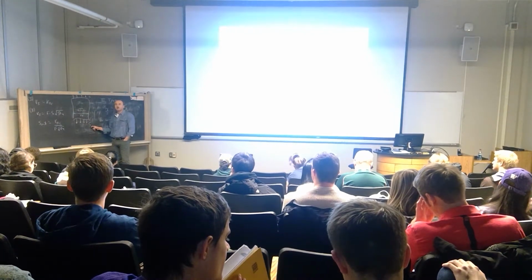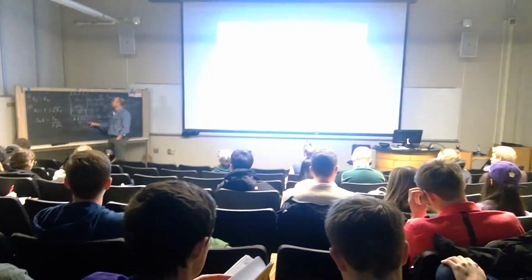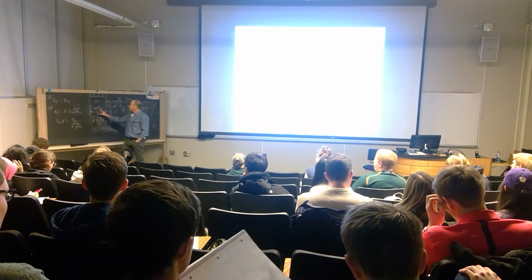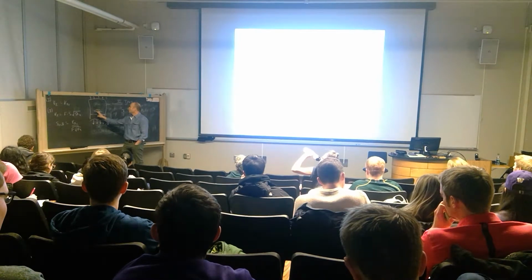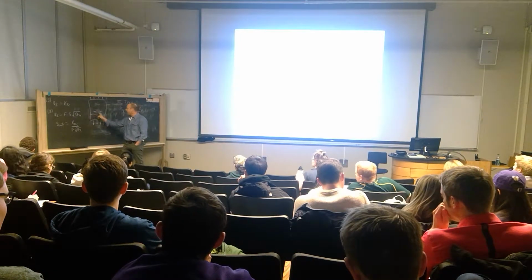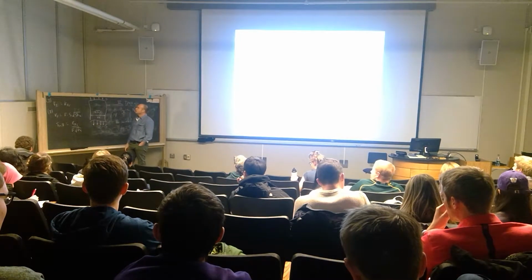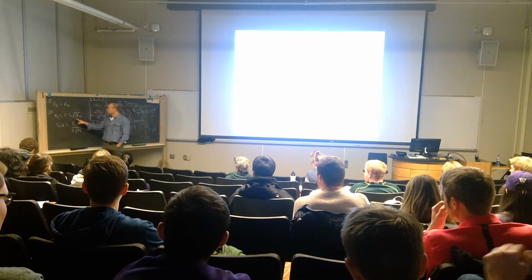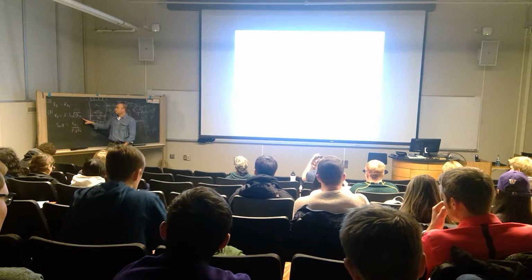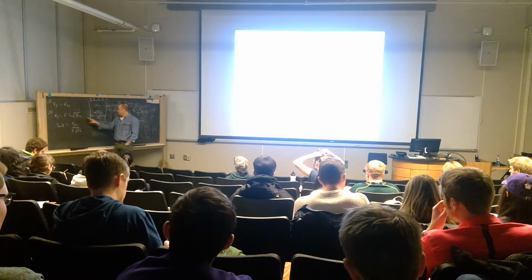Stress, the maximum value of tension, which I'm defining here as S, the geometry of the structure and the crack, and so I've defined a half width of the crack as A and a half width of the panel as B. And this we define the stress intensity for that particular condition. Okay?